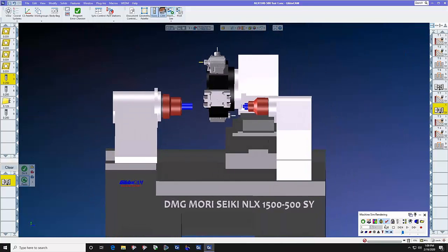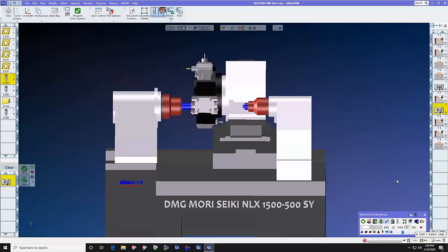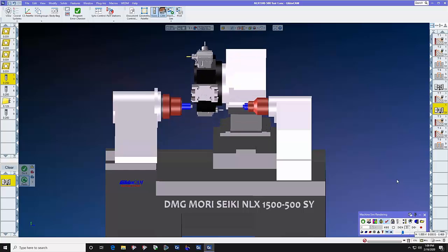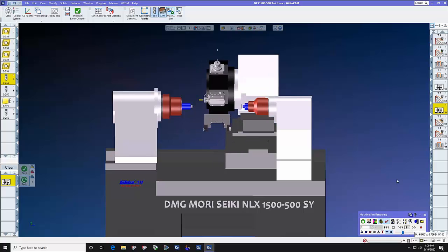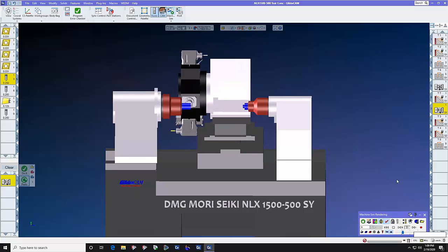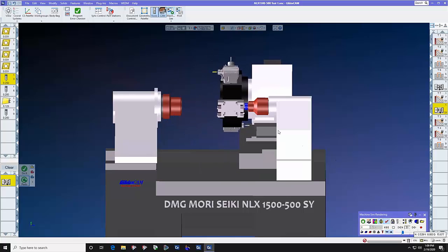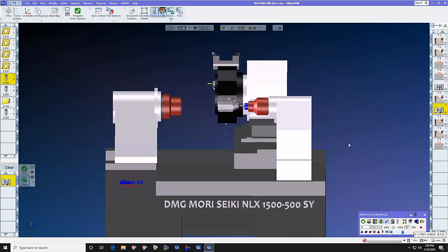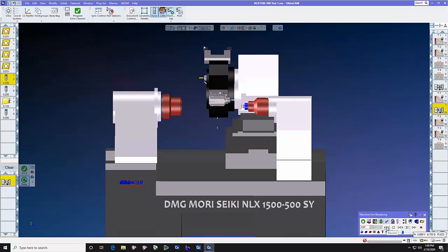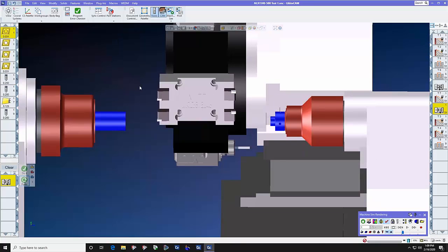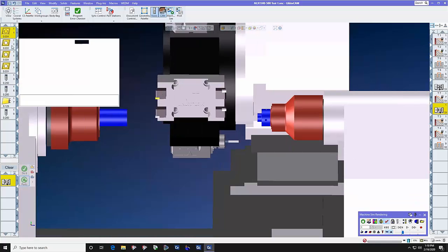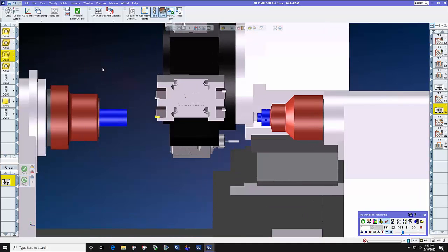Let's watch this part run one more time so that you can see all the things that we've covered, and you can also see that this quad tool holder is automatically commanded to move in the Y-axis by GibbsCAM because GibbsCAM understands where each of those 4 tool tips are. As soon as the part file is done running, I will show you how we identify the tooltip position. And here, we're going to go back to rewind, and the top of the program, if we click on Tool 1 and force a redraw, Tool 1 is highlighted in yellow, and so on.